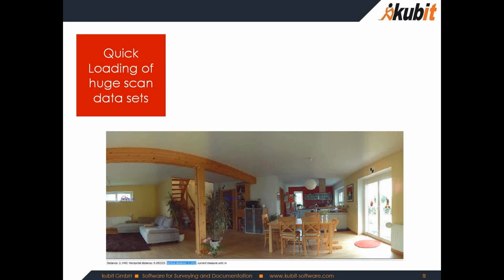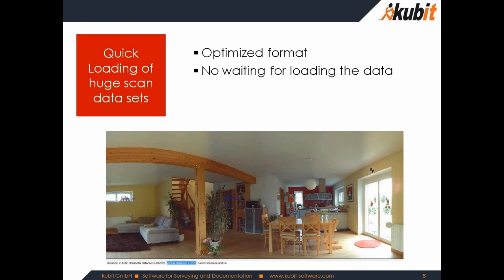So quick loading of huge scan data sets. We're going to be working in this optimized format, which is going to really allow us to load a scan file very quickly, so they're not going to be waiting around for data to load up. As far as imports currently, you can import PTZ, FLS, FWS if you have the full Faro project file, RSP from Riegl, and PTX files. And these are per scan position files.